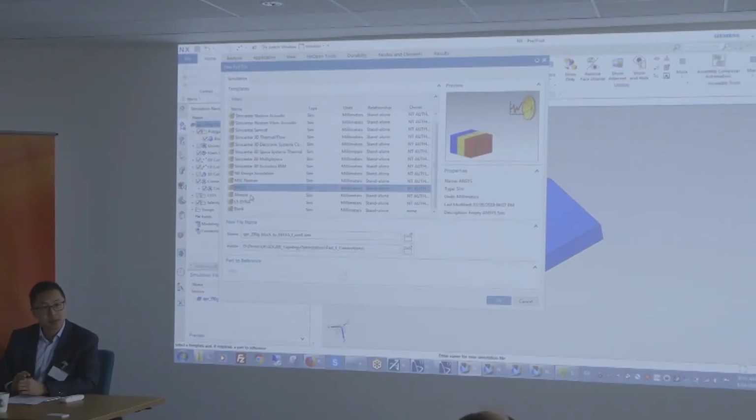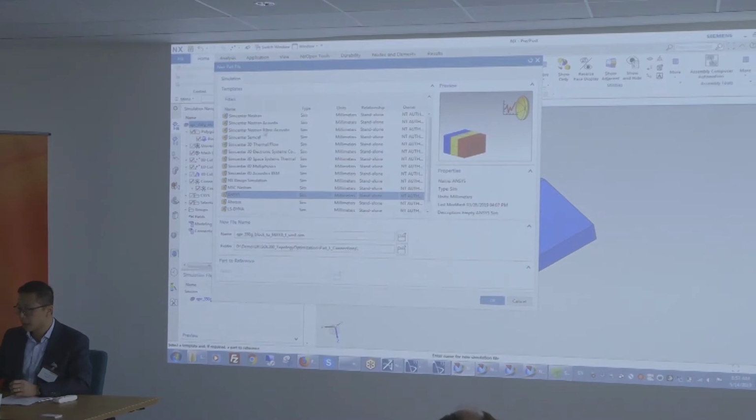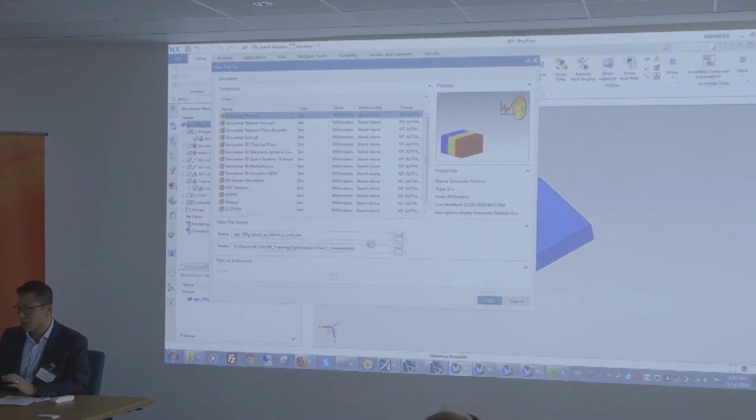But the easiest thing for us to prove that is to actually see the input file, the input deck. So the INP for the Abaqus, or the PDF for the master, or the DAT file, yeah. The deck file. Can we see that? Because I know some of these codes hide it. Yeah, in this case, you can actually see it.